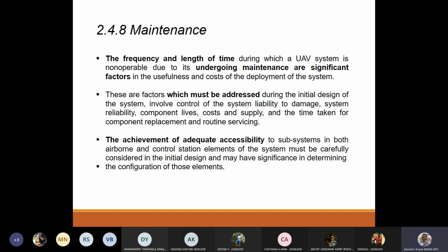And how long this can be supported, how many times you can support it for maintenance. If you talk about a normal UAV, 200 maximum takeoffs and landings, correct? So a 2 kg, 3 kg or 10 kg aircraft flying for 100 takeoffs and 100 landings, or maybe 200 takeoffs and 200 landings, that is fine. Going more than that is not useful. You can either discard it, or you can reuse the electronics for other models, other structure models, correct? So you are going to talk about the number of takeoffs and landings, or you are going to talk about time, correct? How long this can survive.